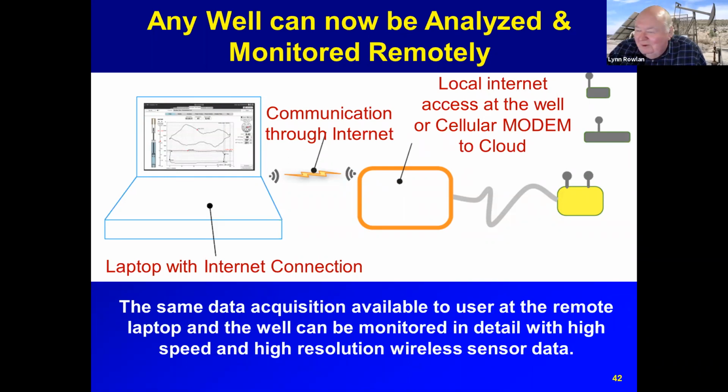Normally, when you have a rod pump well, the fluid level is at the end of the tubing. Even in a horizontal well, the pump won't pump unless you have fluid near the pump. And sometimes the fluid level could be above the pump. But in gas wells and plunger lift wells, the gas flows up the tubing to the plunger, and often in a horizontal well, the gas is on the top and the liquid's on the bottom of the horizontal. And so sometimes when you shoot a fluid level, you can see out into the horizontal and see perforation upkicks.